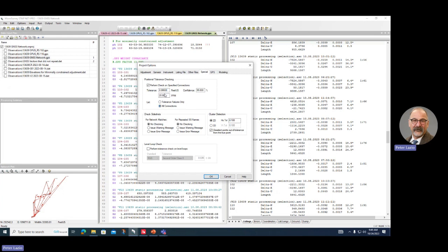And this will come into play later on because I wasn't quite able on some of the shorter baselines to get my 20 parts per million. But with the combination of the total station thrown in there, I was able to get everything below it when I did my connections and checked them this way. So that's how I'm going to argue it in my control report.